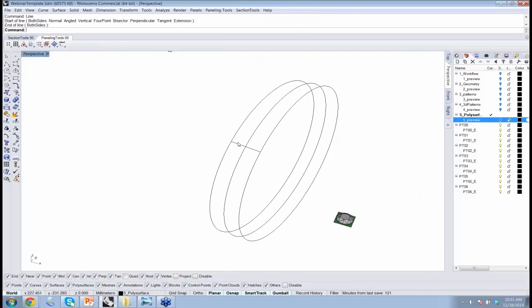Let's say I want my V direction to be perpendicular, the direction of that little line that I just created. Now I have to move the start point or the seam of each one of these curves to match. And I also need to know that the direction of the curve is going in a similar direction. So curve point in Rhino, or curve seam. I select my closed curve, and you'll see how the seam is actually showing to be down the bottom there. I'm just going to drag it to the new location that I'm happy with.